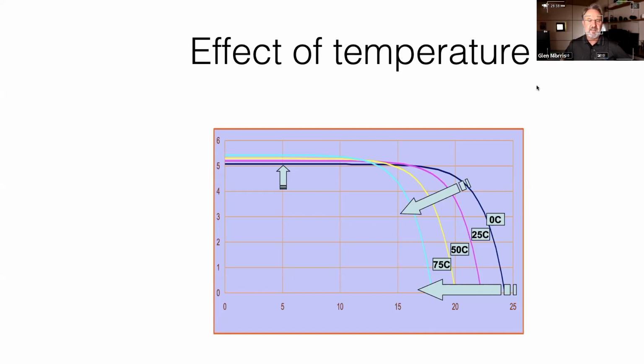There's degradation due to sunlight, which varies with technology as well. So ironically, not all solar panels are really excited about being in the sun. Some of the organic thin film modules actually degrade pretty quickly in the sun. We're looking at lifespans of like 2 years. So they'd be more suitable for disposable applications, maybe emergency sites where you just want to throw up a system and then dispose of it afterwards.